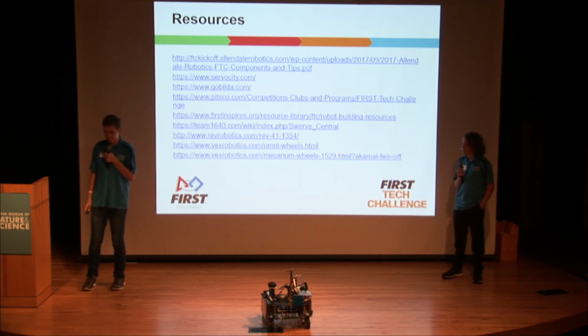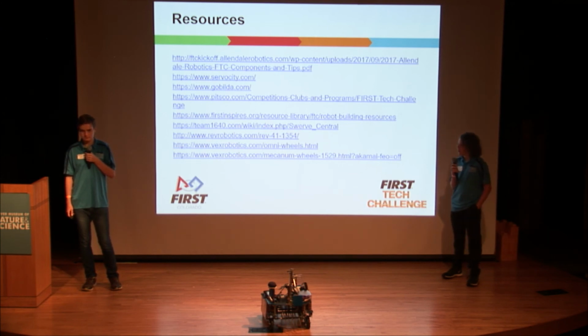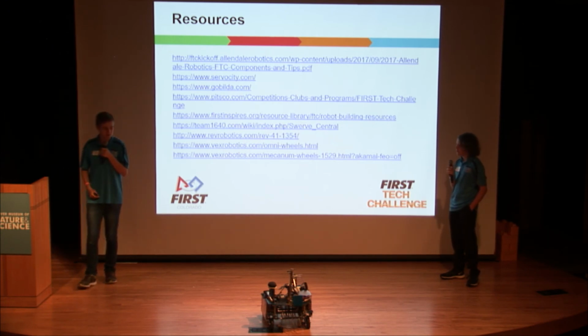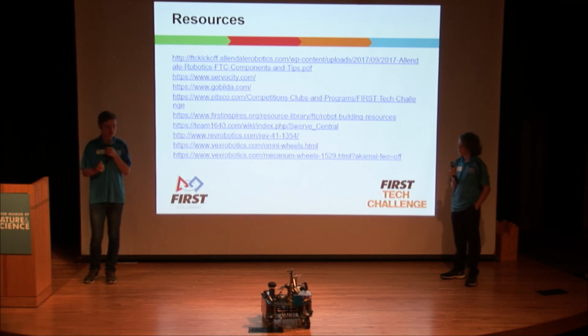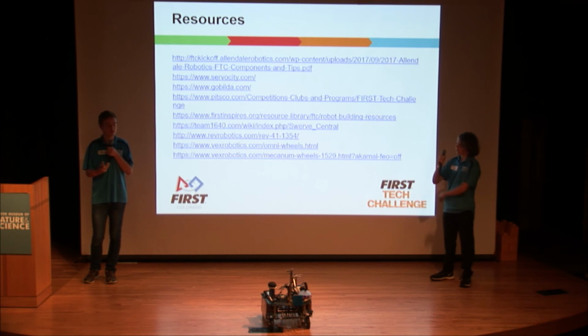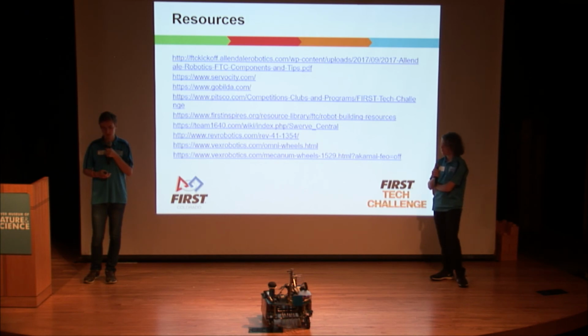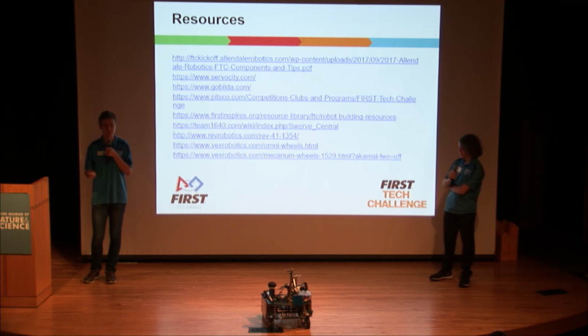Can you talk about the difference between set screws versus clamping hubs in the use of the chain? That is something I don't think we have a lot of experience on. We used bearings that have set screws in them to tighten, and that's what we used on our shafts to keep them where we wanted them to be. But clamping is another option, and that's something we don't have expertise in. I guess it's more relevant with these shaft hubs versus the hex. We used hex shafts and hex shaft hubs.